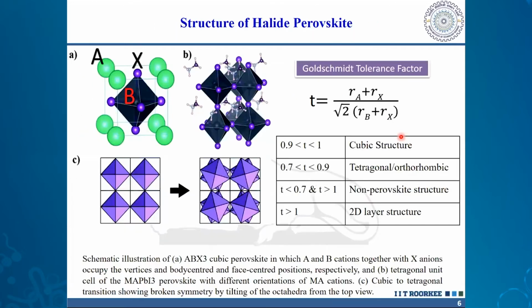Now if we look at the crystal structure of perovskite, a standard organic-inorganic perovskite crystal structure looks like this, where we have these octahedra, especially corner sharing octahedra. And when these corner sharing octahedra meet each other, they create a void at the center, and this kind of cuboctahedral void encompasses the organic cation.